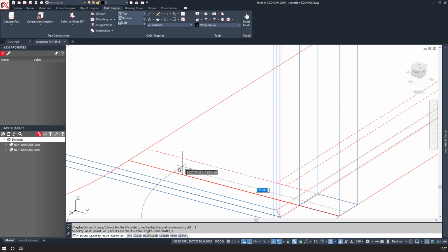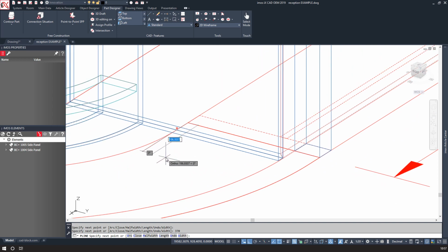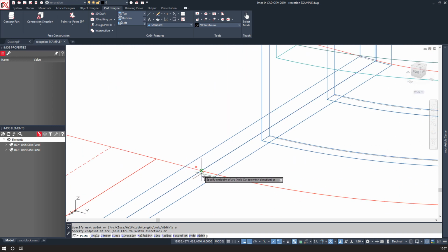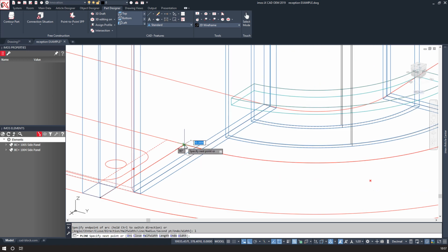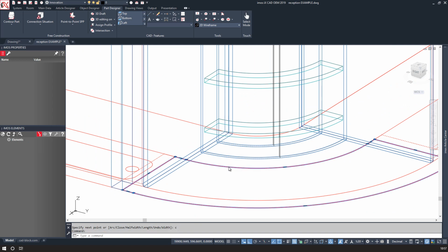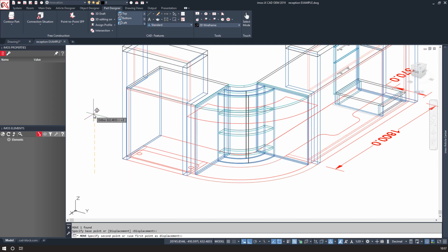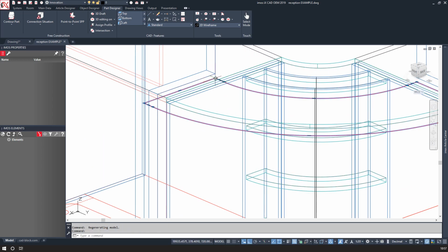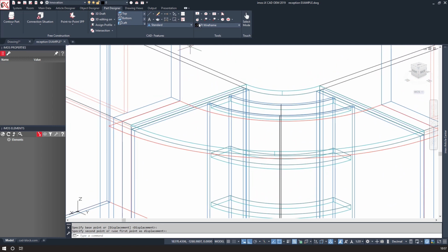We'll make some decorative worktop, I think this is, or some sort of addition to the existing worktop to make it look like the thicker material is running all the way around. So I'll use the same tool as before, the polyline tool, and I can switch between line and arc segments within the polyline by using L and A and pressing enter in between, and then C to close it. And I'll just move this up so that it's in exactly the correct position. This looks good.